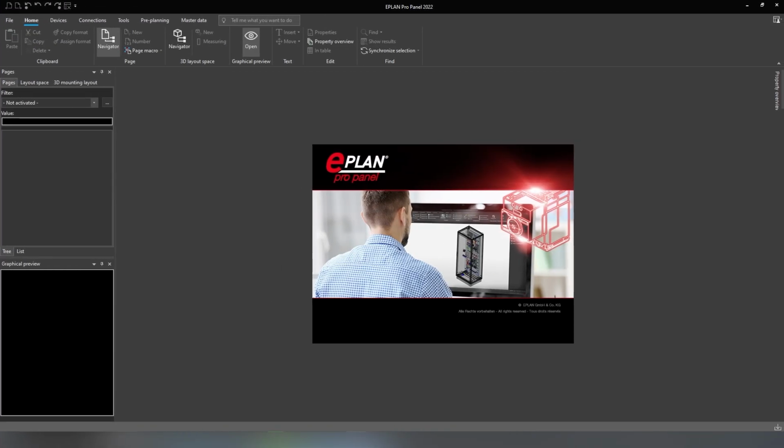Hello guys, so today I want to speak to you about EPLAN project types and also about EPLAN page types. So we know that in EPLAN you have two different types of projects: the schematics projects and the macros projects. The schematics project is the commonly used type of project, and then you have the macros project. This is used for creating and generating macros, schematic parts to be used later in the schematics project.